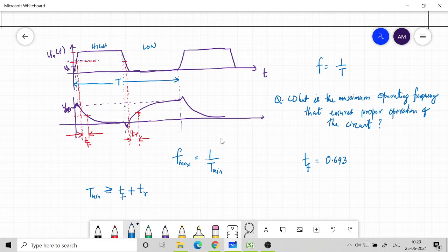That was basically the logarithm of 2. 50% means the time at which the output becomes half. So the logarithm of half will come, and if you take the inverse of that, it is log 2, and log 2 is 0.693. So fall time is 0.693 Rn C out, according to this definition.